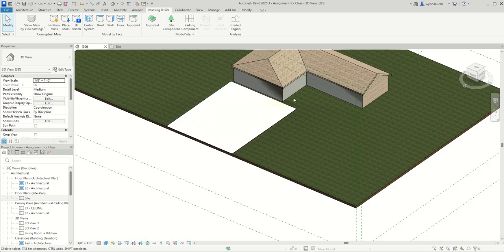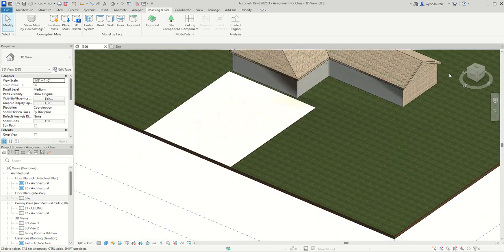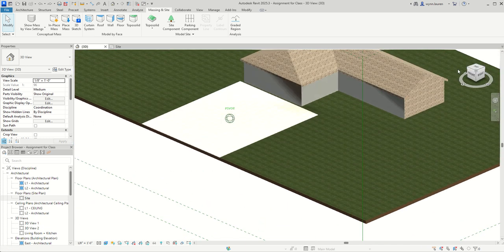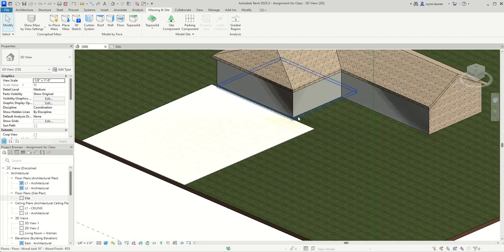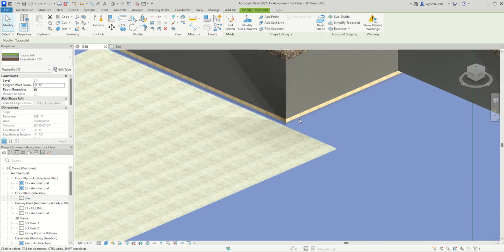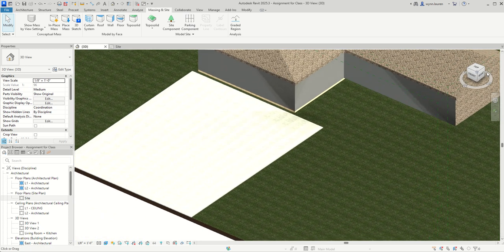Another thing you can do is, if you notice this, the grass kind of intersects the building at the top of the floor. So you start to understand there are different properties going on. If that's something you don't want, see how the floor is kind of underneath. You can also select the entire surface and create an offset of -6 inches or something, and it'll bop it down. Then you can see the floor structure.